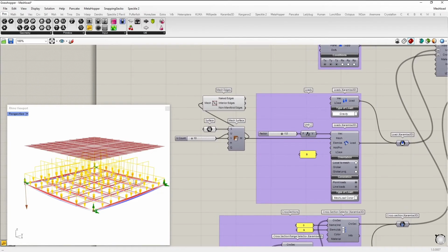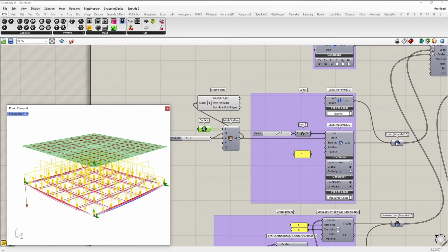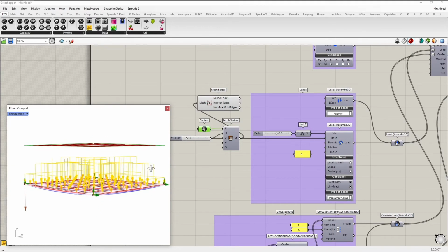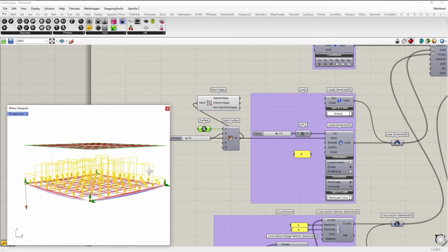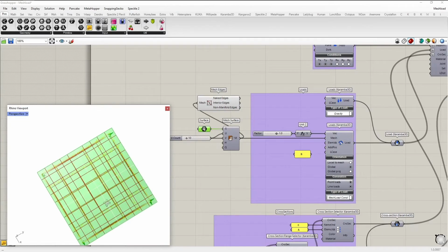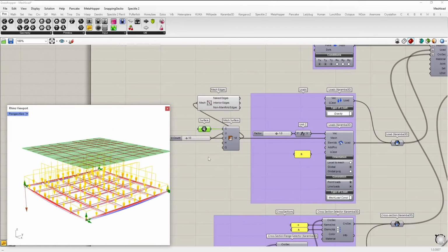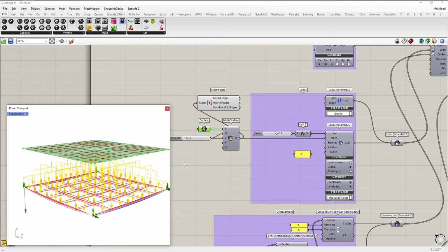We apply the mesh load using this meshed surface, and you can see we have a relatively coarse mesh and an uneven distributed load, even though the surface which this mesh is based on is the same size as our grid below. This is because Karamba calculates mesh loads using the mesh faces. The calculated mesh load gets applied to the closest element.